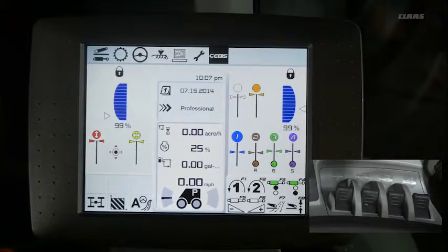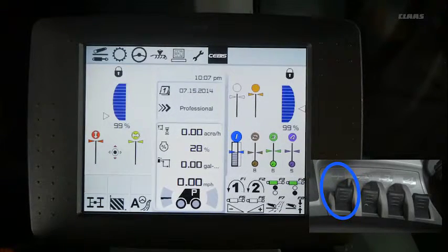If a more gradual flow increase is needed, you can set a ramp-up flow or response time flow. The blue valve has already been set up for this function. This controlled ramp-up is useful if you want to reduce shock loading in your hydraulic system, for instance if you're trying to bring an orbit motor up to speed gradually. When we engage the blue valve, watch as the flow climbs gradually until it reaches its pre-assigned flow control setting.